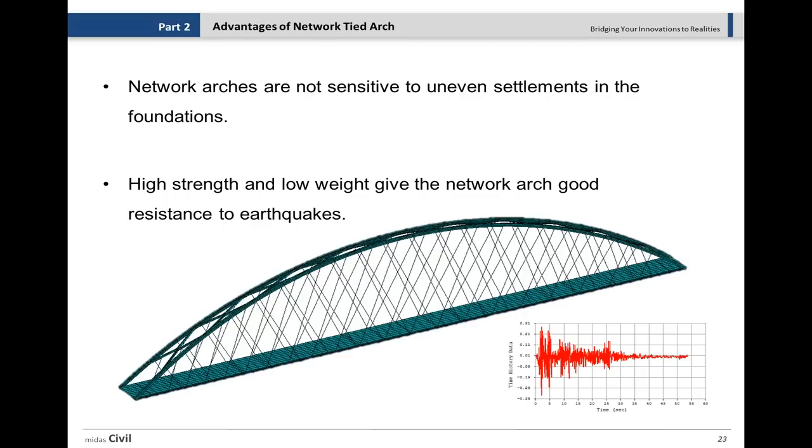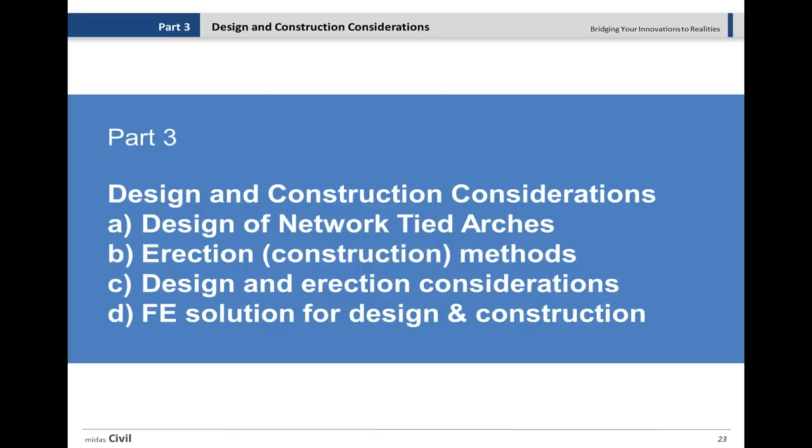More on advantages of tight arches. They are not sensitive to uneven settlement in the foundations, again because of their stiffness and the more redundancy. And also their higher strength and low weight give the network tied arches a good resistance for the earthquake. So they behave pretty well under the seismic forces.